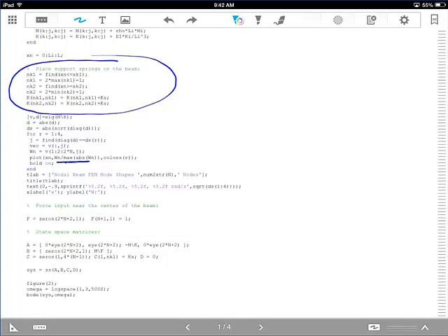and the frequencies that come out of it. Now, of course, we're interested in whether the system has a zero, so to speak. Can we introduce a zero in the system such that when you're forcing it at a certain frequency, there's no transmitted force to the base? So we have to make a state space system from that.